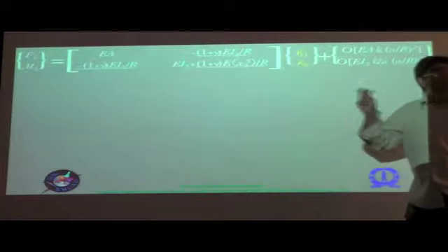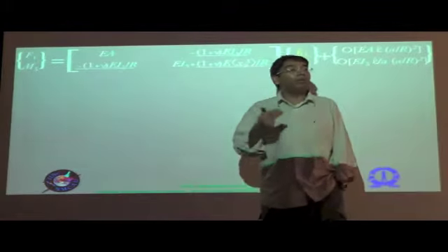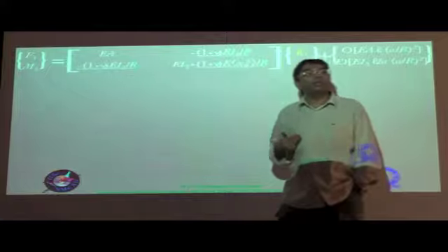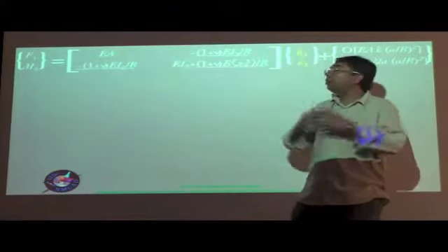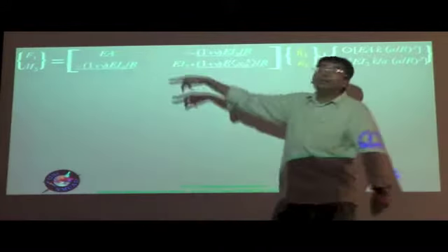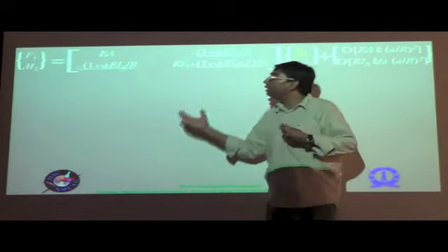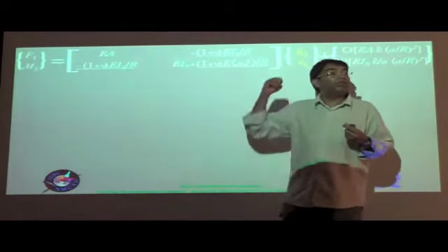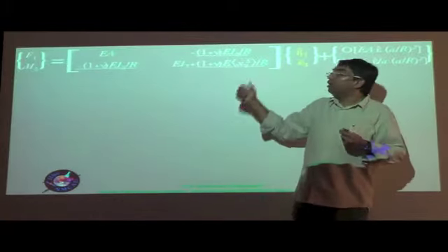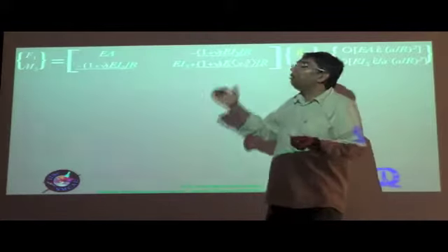Okay, so let's summarize that in matrix form, whatever result we got in the previous slide, the two derivatives that we took of the energy per unit length of the beam with respect to gamma 11 bar first and with respect to kappa 3 bar. Those are the two equations. We are clubbing them together in this matrix equation. So there you see that this is the so-called 1D stiffness for this example. It's a very simplified example because we didn't consider transverse shear strain, therefore F2 and F3 are not appearing here. We consider only planar deformation, so M1 and M2 are out of this problem. So only F1 and M3 are there.